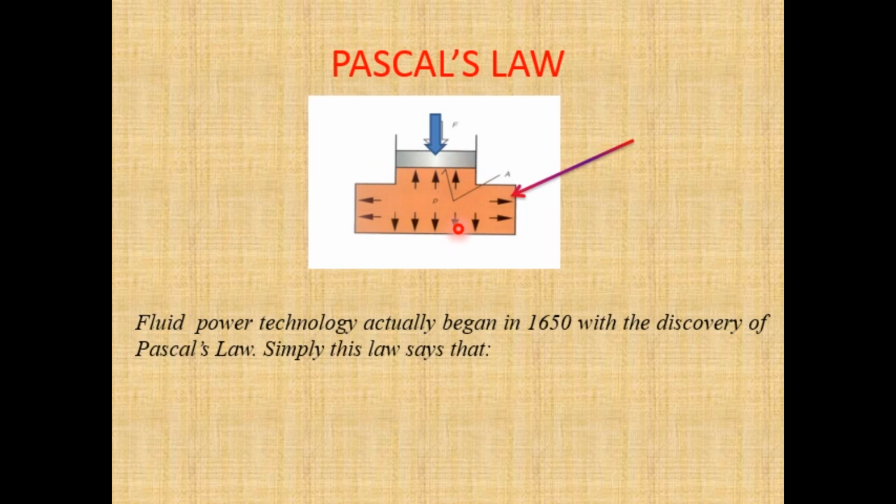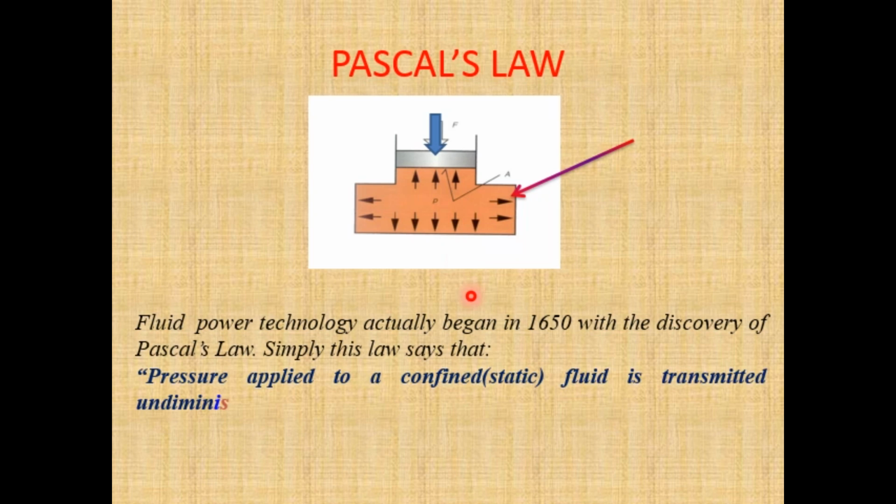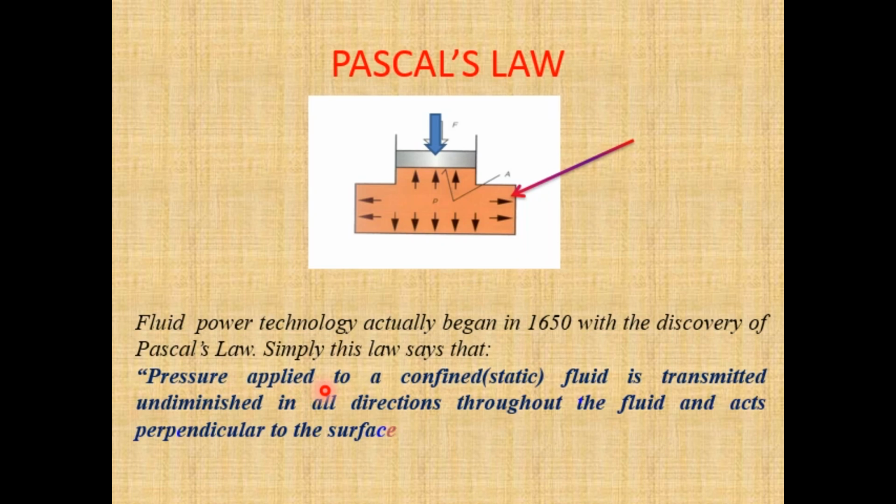All these things that I told you, when we combine them together and put them in the form of a sentence, become Pascal's law. So what is Pascal's law telling? It's telling that the pressure applied on a confined fluid, and a confined fluid is a static fluid, a fluid at rest because I have kept it inside a container, is transmitted undiminished in all the directions. So without any losses, it is transmitted undiminished in all the directions throughout the fluid.